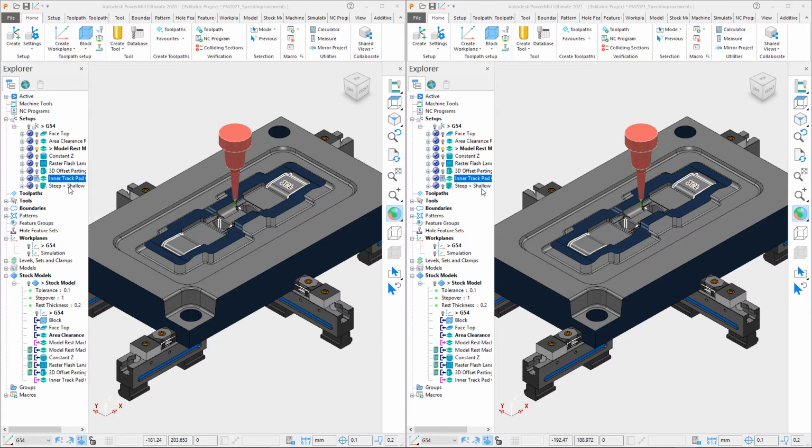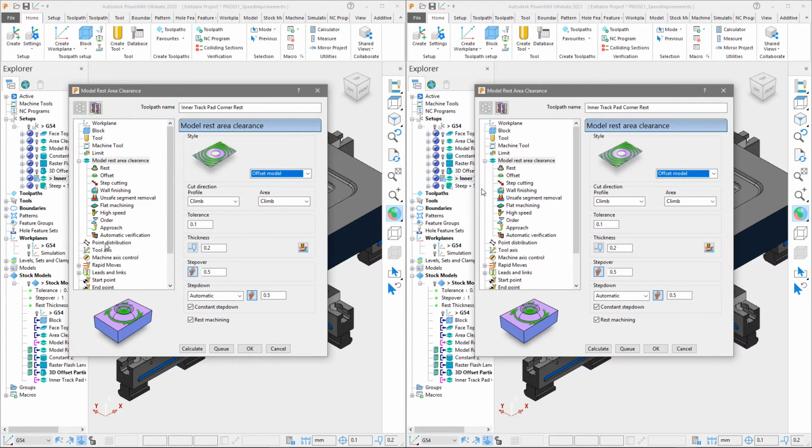We'll move to the final uncalculated toolpath, access the settings and calculate. This is another rest machining toolpath, but since we have now added some finishing operations to the outer regions of this forging die, we need to calculate the changes in the stock model. We are using a 2mm ball nose tool and are limiting the toolpath to stay within a rest boundary to tackle most of the remaining material to be roughed. So we must calculate a stock model, rest boundary, and then the toolpath itself.